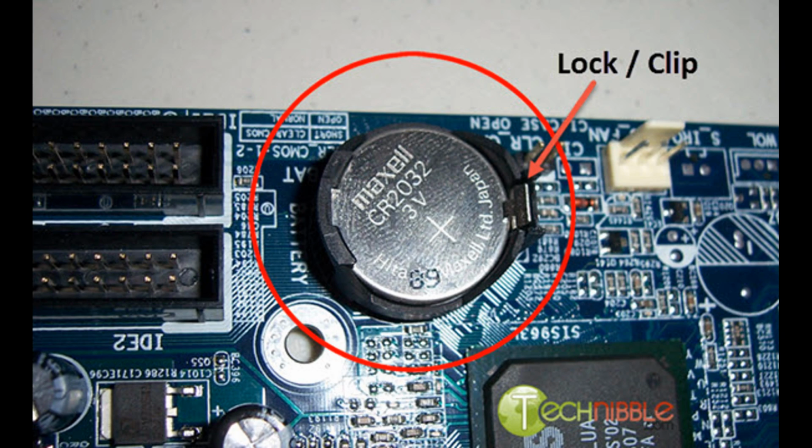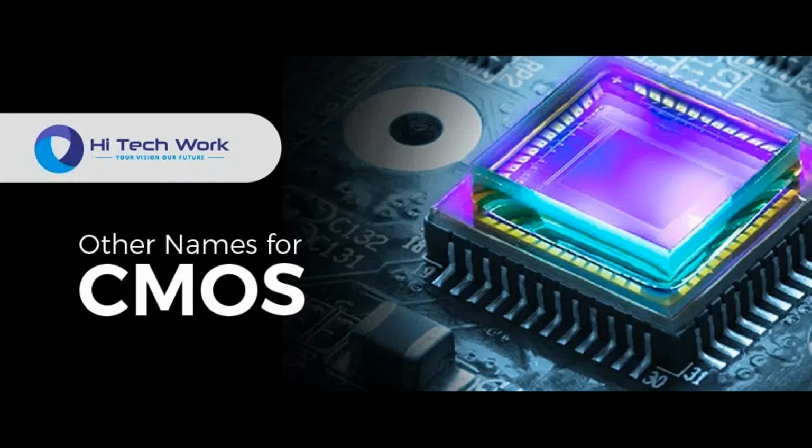Power efficiency. CMOS circuits offer excellent power efficiency because they draw significant current only during transitions between logic states. When a gate is static, not switching, it consumes almost no power because either the NMOS or PMOS transistors are in the off state, providing a high impedance path between the output and the power rails. Complementary operation is a cornerstone of CMOS technology, enabling the design of high-performance, low-power digital integrated circuits used in a wide range of applications, from microprocessors and memory chips to digital signal processors and other digital logic circuits.